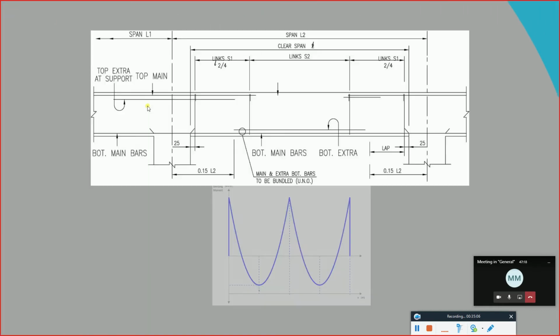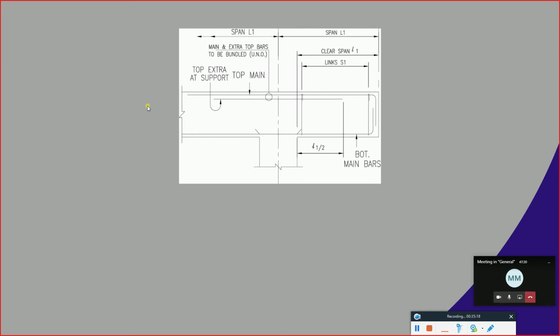Okay, so beams and slabs are almost the same. The only difference is in the values due to the curtailment conditions, and that we don't have the second reinforcement. This is a cantilever, exactly the same concept as the slab. Reinforcement for the bottom goes from the beginning till the end. Since it's a cantilever, we are going to provide the top reinforcement for the full length of the cantilever. If that top reinforcement is sufficient, then it's fine. If it's not sufficient, then we need to provide extra reinforcement here. How much is the length? The length is going to be around half of the cantilever portion.